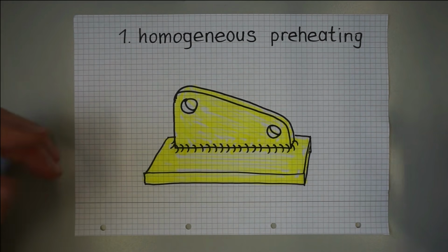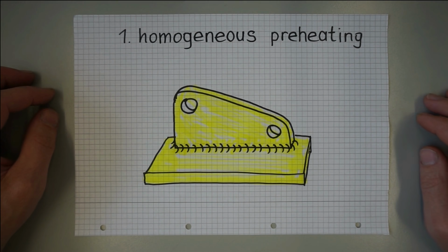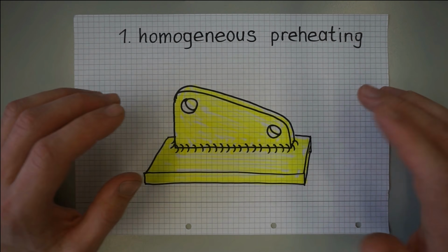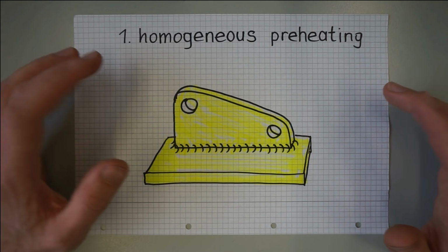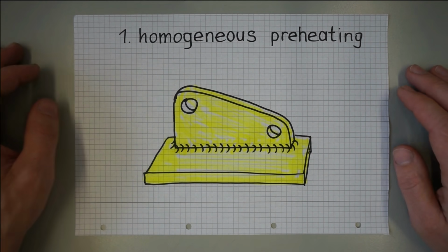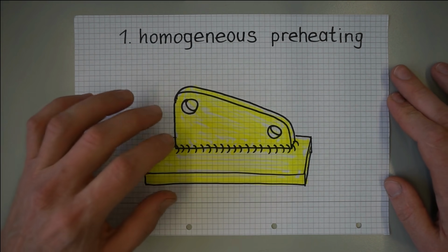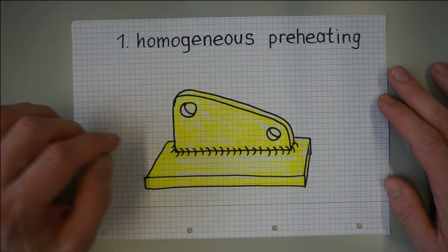We may keep in mind that the higher the preheating temperature, the smaller is solid body distortion. In theory, we can even get rid of distortion if we preheat the workpiece close to melting temperature. By the way, this was historically used to exquisitely weld cast iron, which otherwise may severely suffer from cracking. But of course, there is a natural limit for the preheating temperature.